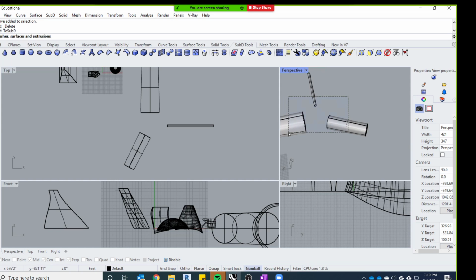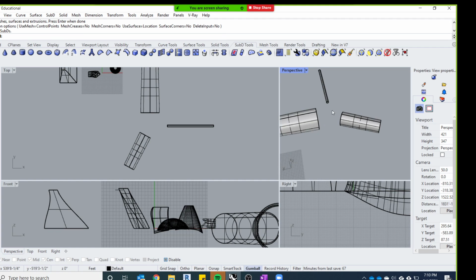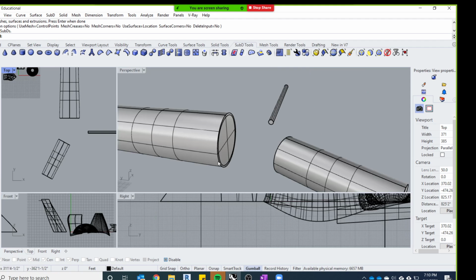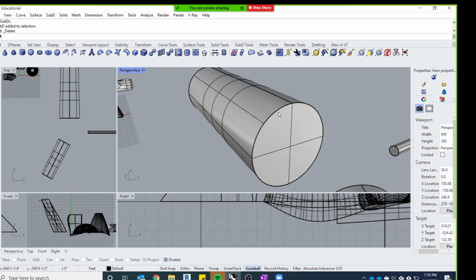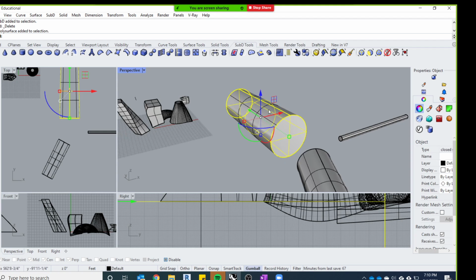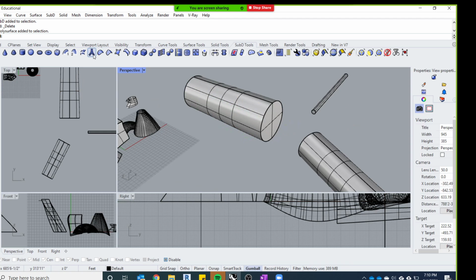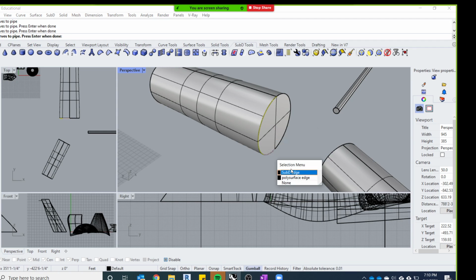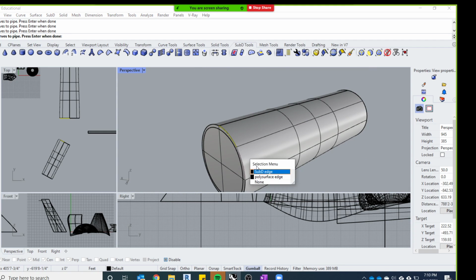Okay, yeah, so I can select these objects, right click. You can mess with those divisions, but it's now converted these 3 things into a sub D object. So if I come in here now and I wanted to connect them, let me just move this guy, that's probably fine. So I can now use that bridge command and I can start to imagine connecting these together. So I can select these edges and I can select the same edges on this one.